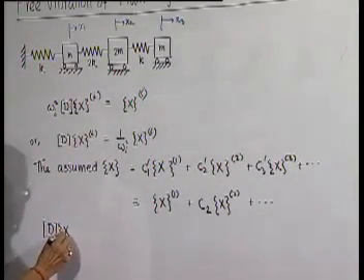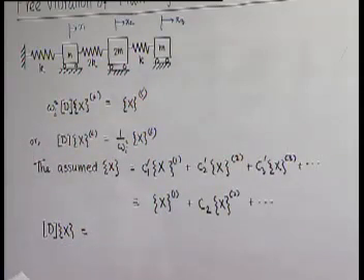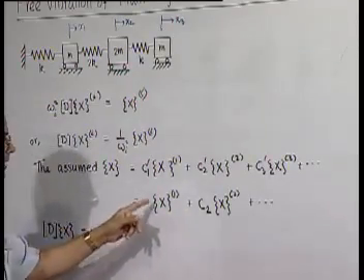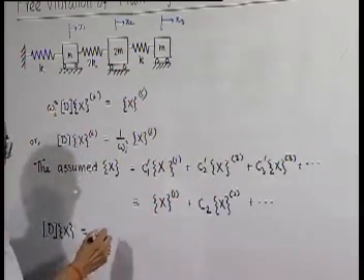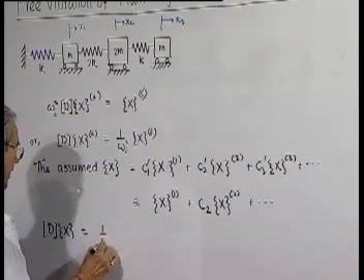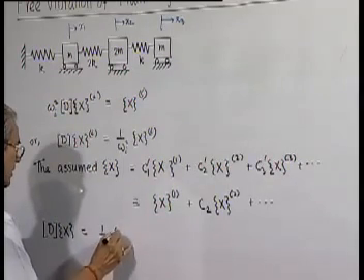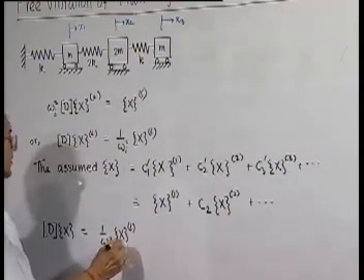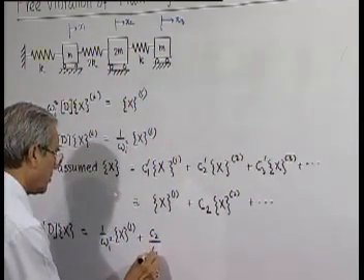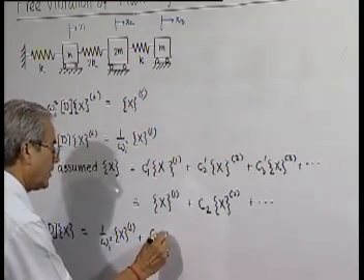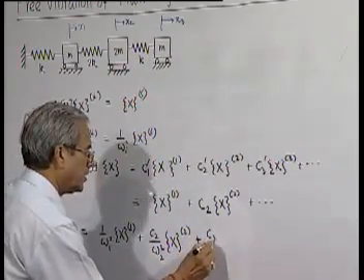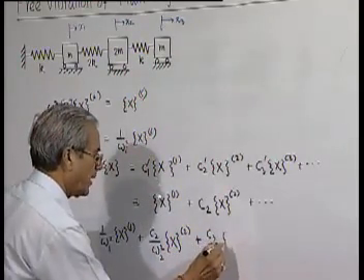Fine. So now if I apply this D into x, that means when I pre-multiply x by D, what does it mean? I am pre-multiplying each one by D. Now, since this is a natural mode, when I pre-multiply this by D, I will get 1 by omega 1 square x1 according to this rule plus C2 by omega 2 square x2 like that, C3 by omega 3 square.